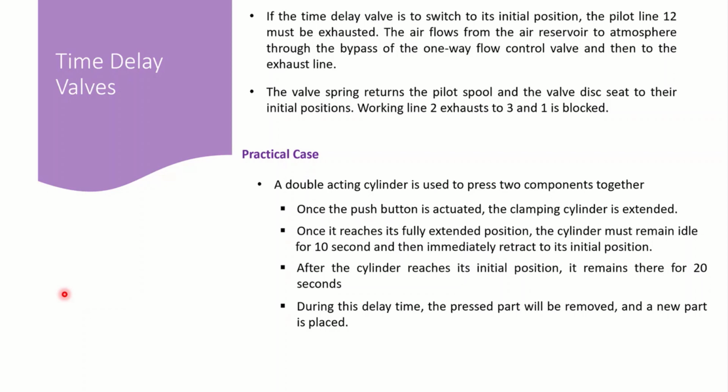First, we need that delay for pressing, and then we need another delay in order to have another actuation mechanism which pushes the pressed components inside, let's say, an output chute, right? So that is how a time delay valve can help us inside a pneumatic circuit or for a practical application.